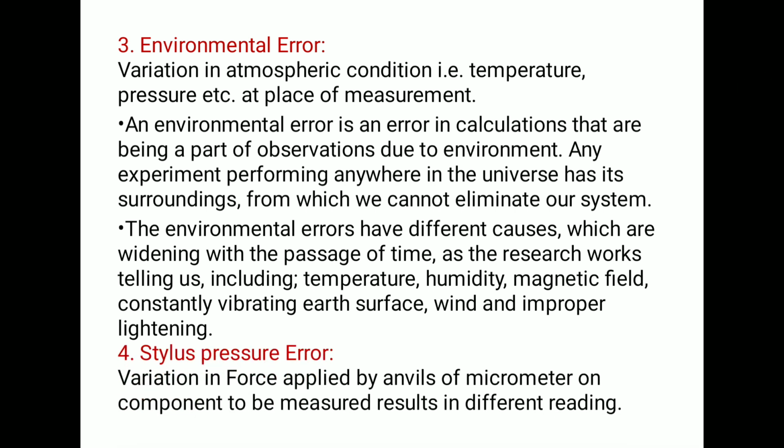Then the fourth one is stylus pressure error. Variation in force applied by anvils of the micrometer on the component to be measured results in different readings. So this is also one type of error, stylus pressure error. So this leads to wrong results.